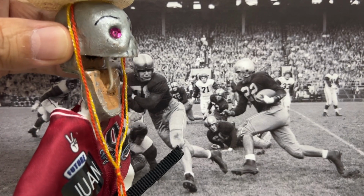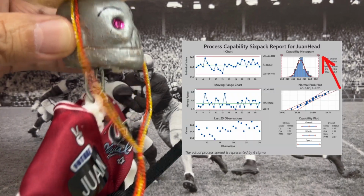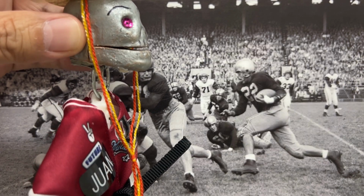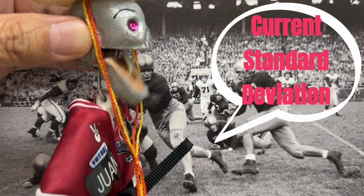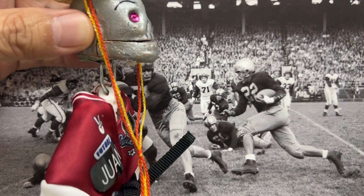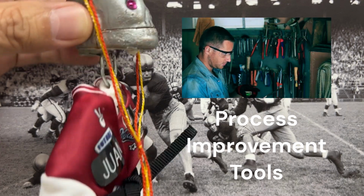Reverse capability is a very useful tool to calculate your print or specification limits if they are not known or need to be established. But be careful, this technique only allows you to establish the limits with the current standard deviation of your process, and if you're trying to reduce your standard deviation or variation of your process, you need to use a different tool for process improvement.